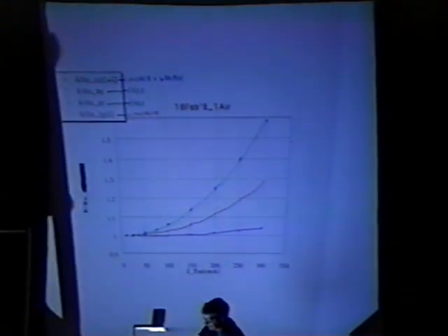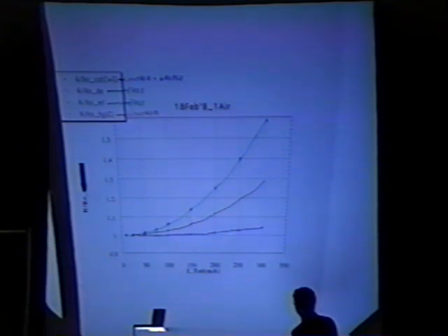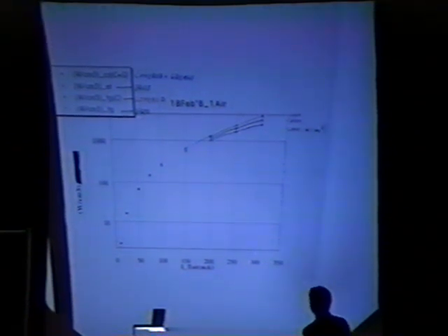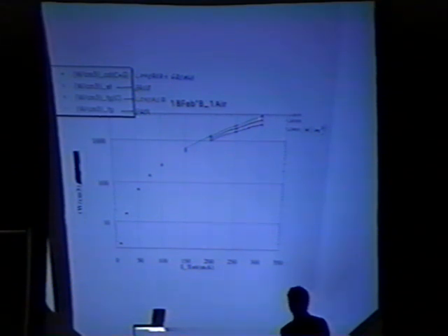It's equivalent to the effect of resistance increasing: with the covering, larger resistance increase, and the cover alone gives a lower one. It is intermediate, just covering in air. Just an idea, the power dissipated in the system, in the cover, at 300 milliampere in air, we have about 4,000 watt per cubic centimeter, and it doesn't break. So it's a good point for other future applications, our power density.